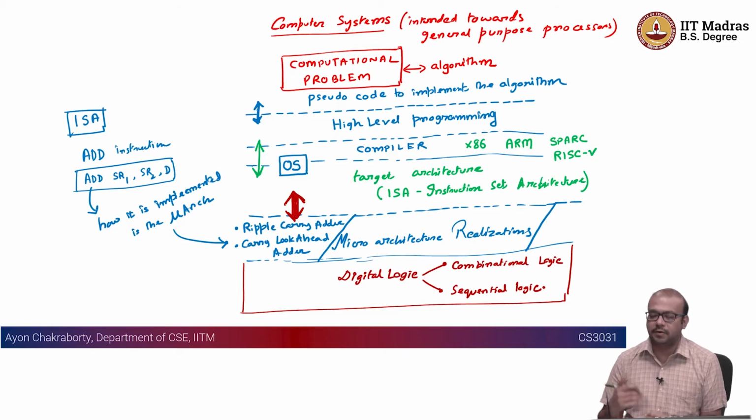So the delay of a combinational logic can be computed in terms of gate delays. So you have some inputs and you have some outputs, right? And this is not going to be carried forward into the next clock pulse, something will happen, no dependency, right? Whereas sequential logic is something where the previous output is going to influence the next input or the next output, okay?